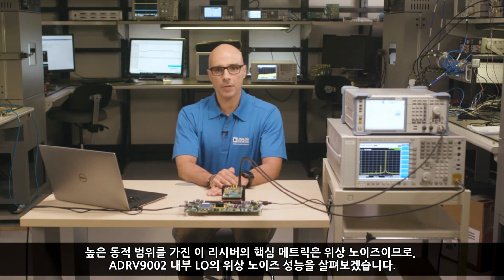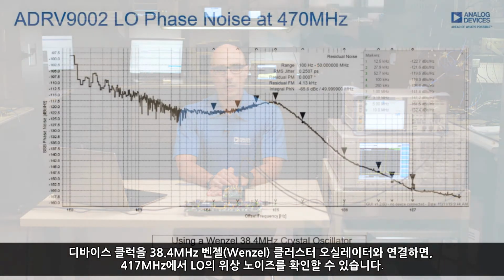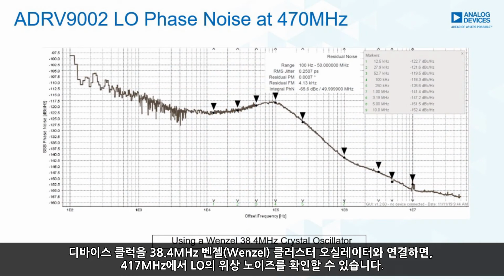A key metric in a high dynamic range receiver is phase noise. So let's have a look at the phase noise performance of the internal LO of the ADRV9002. With the device clock connected to a 38.4 MHz Wenzel oscillator, this is the phase noise at 470 MHz LO.